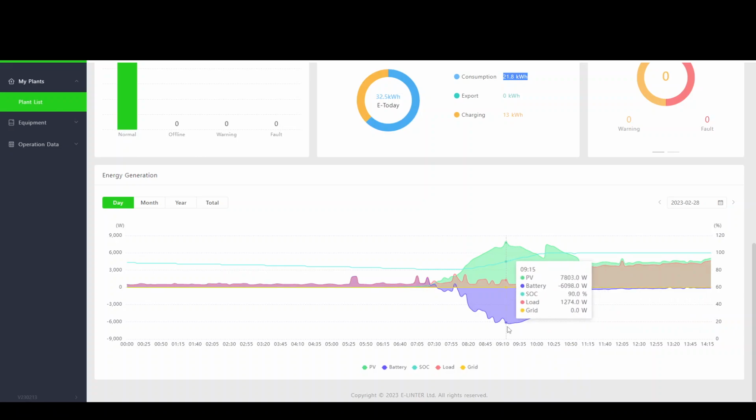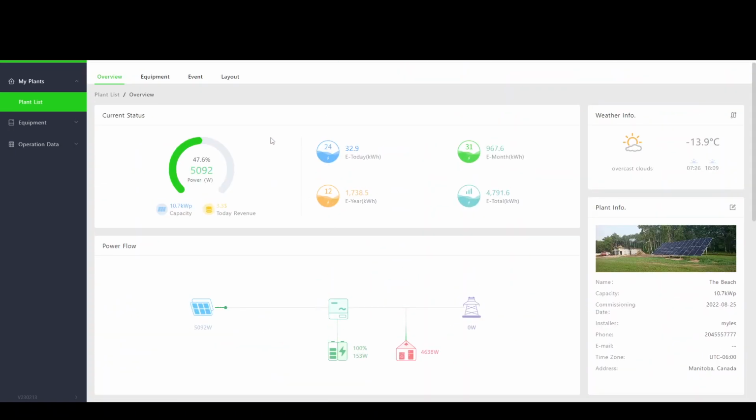And you can see your charging profile here, the tailing current on the bulk charge starting to drop. And if you actually go into the battery diagram, which I'll show you, you can see when it hits float. So I have my bulk charge set to 54.4, which is really low, but I want maximum life out of my cells, not maximum capacity. And I have my float set to 53.9, which is just where they sit to maintain charge for the day. So there's only like 200 watts to 100 watts going in throughout the rest of the day when they are full. So that's the main screen, but there's lots you can do with this.